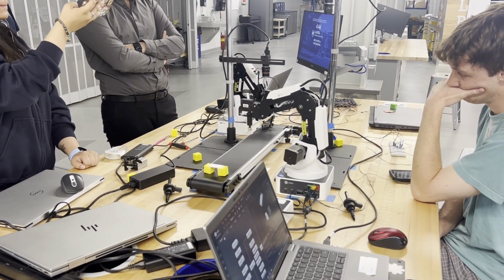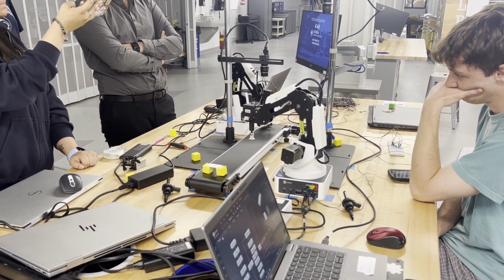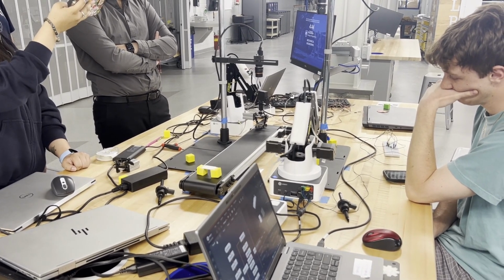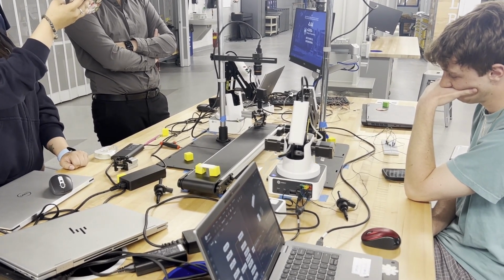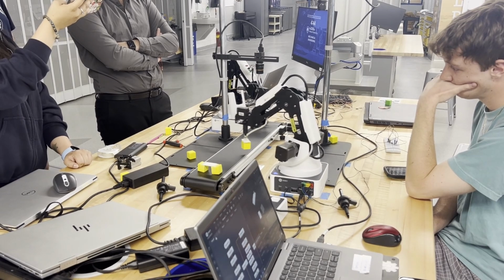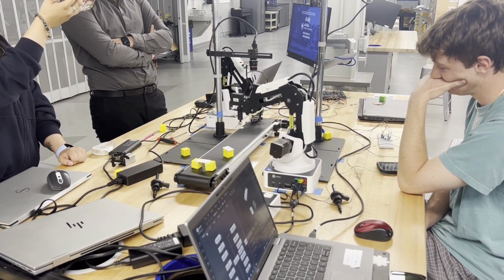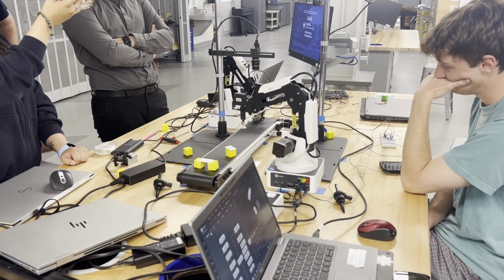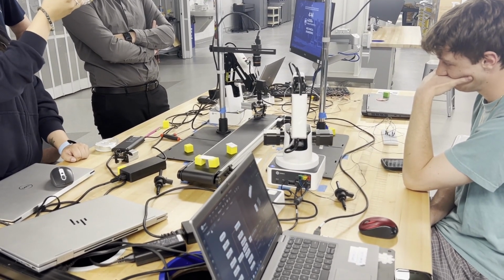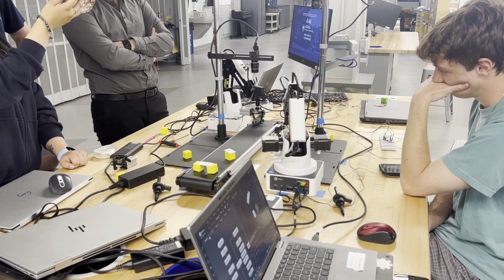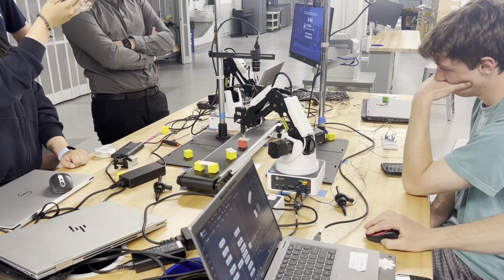Our team mainly focused on the first robot's task. The first step of completing this task was creating calibration files similar to the ones we made in previous labs. We used the fast match function we learned to identify and place the objects onto the belt. Our code utilized the shell module and a random function to place the objects onto the belt randomly, either on the left or right side, but still evenly spaced along the belt.